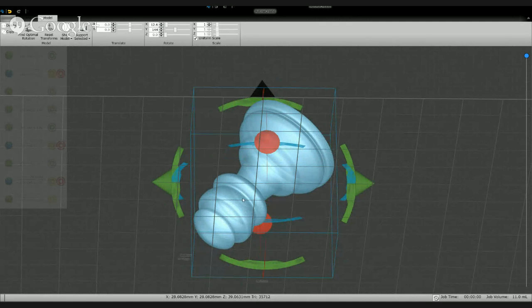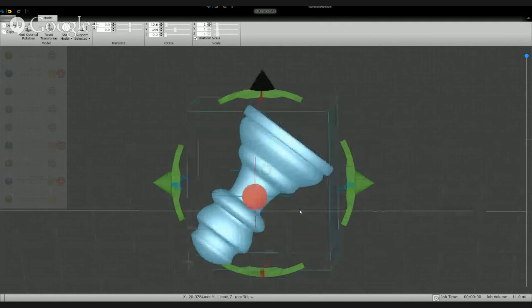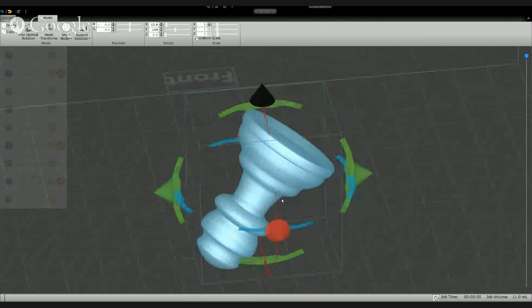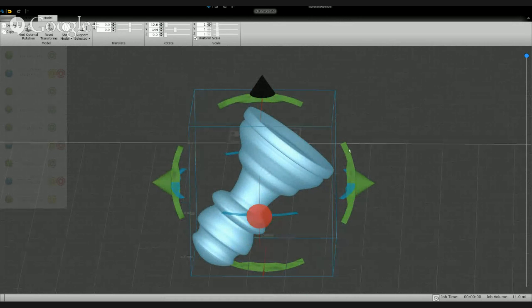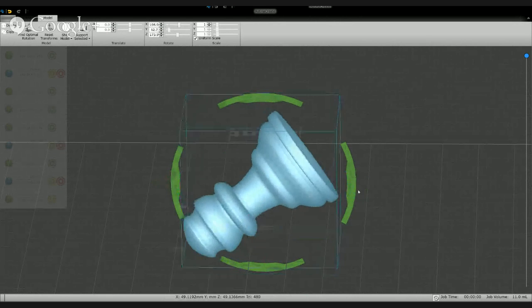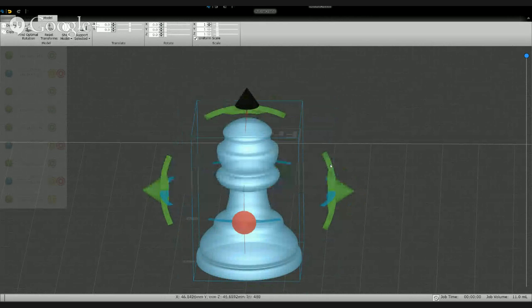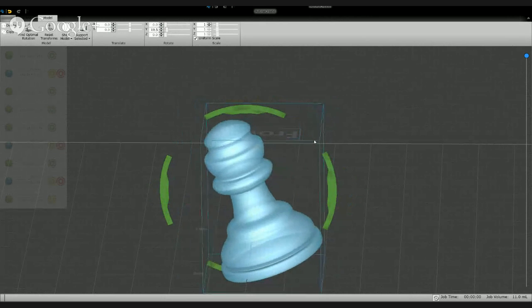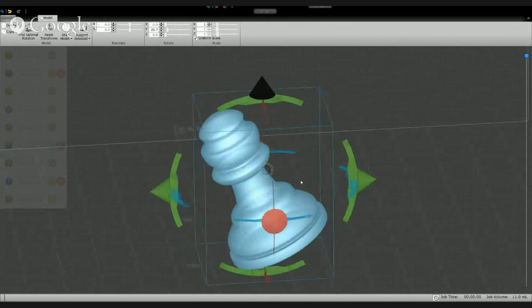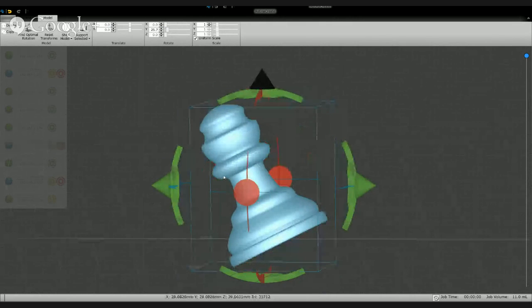instead of on the top. So flipping it upside down doesn't really work for you in this case, but it would if you flip it this way and then support it. It would have the least chance of failing. So the orientation that I would recommend might be an orientation like this, and now you can see that this part of the pawn actually dips downward.